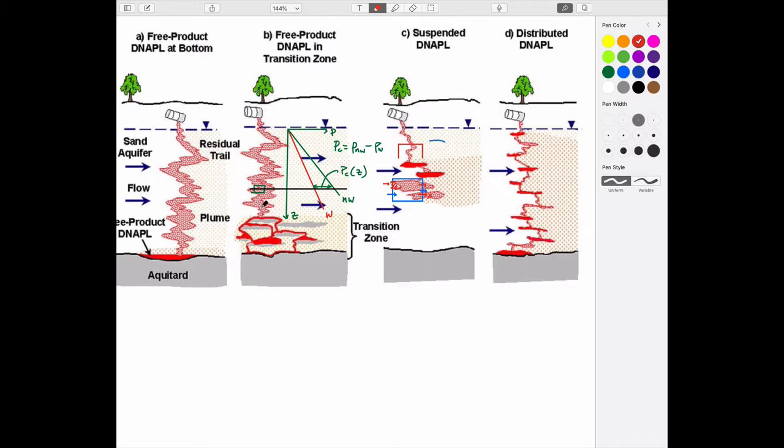And the rate at which it can remove this is controlled in some respects by its solubility, but also by the rate at which fluid can go through it. And so what we'll look at now are the mechanisms by which this stuff, which is ostensibly anchored in place, not going anywhere as a free phase, is very difficult to move as a free phase because you can't suck it out because it's held in so strongly by surface tension forces. What are the consequences of that? If it doesn't dissolve at all, then there aren't really very many consequences because it would stay in place.